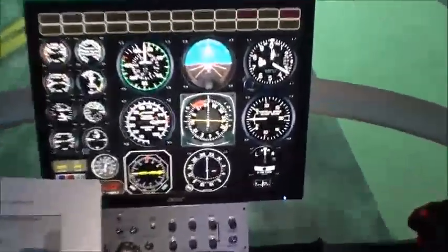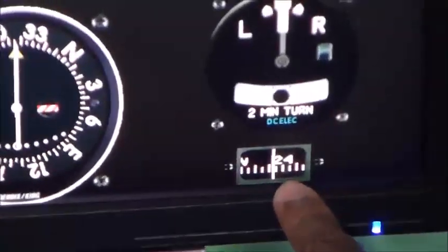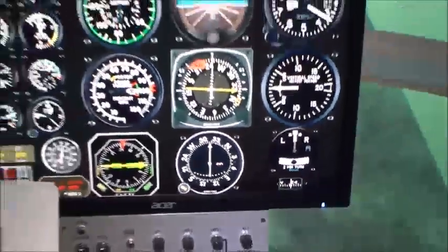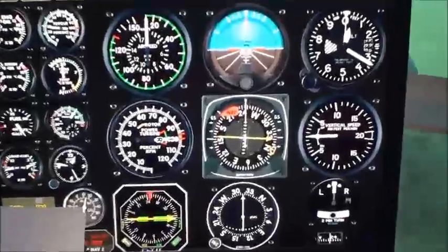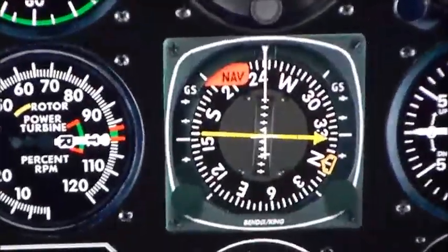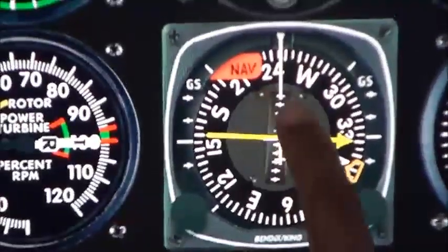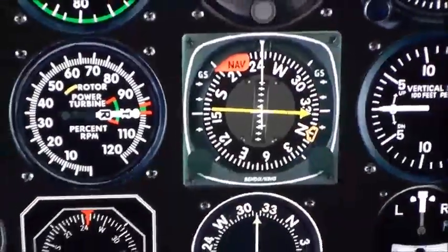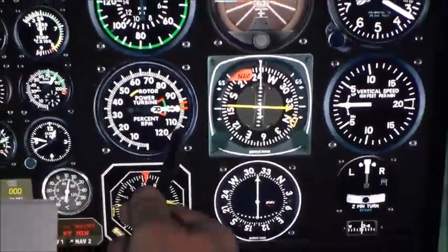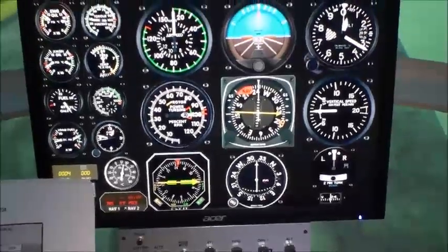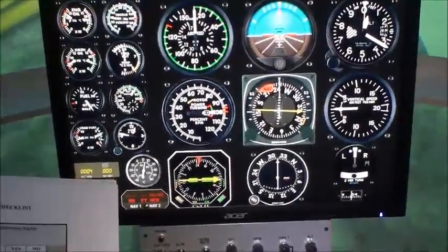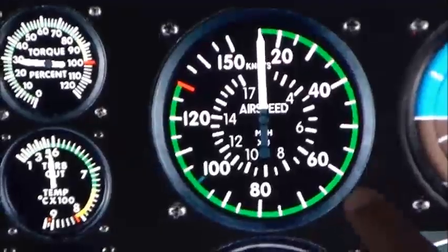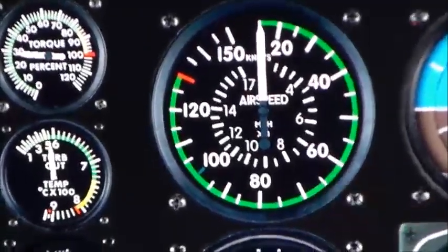Compass, which displays typical incremental markings. Magnetic compass here. And those are 5-degree divisions, right? Yes. Heading indicator with incremental markings each 5 degrees or less displayed in a 360-degree circle. So we have our heading indicator here as part of our HSI, with the appropriate increments. And I see it has a flag on it so that we can make that fail, right? Yes. Airspeed indicator with incremental markings as shown on the aircraft presented. Here's our airspeed indicator.